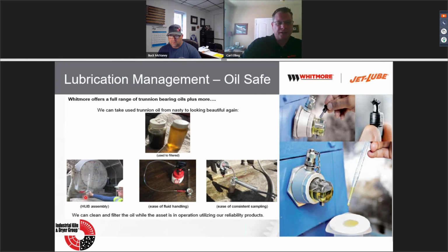This is that hub system. Here's your little bowl where you can see water if you do have water in your oil. And here's a color-coded quick connect. And this would attach to, here's your oil here. Notice the red for the color coding, same label. And here's your color-coded quick connect that would go on to that assembly. And then here's your sample port that you can take samples consistently.